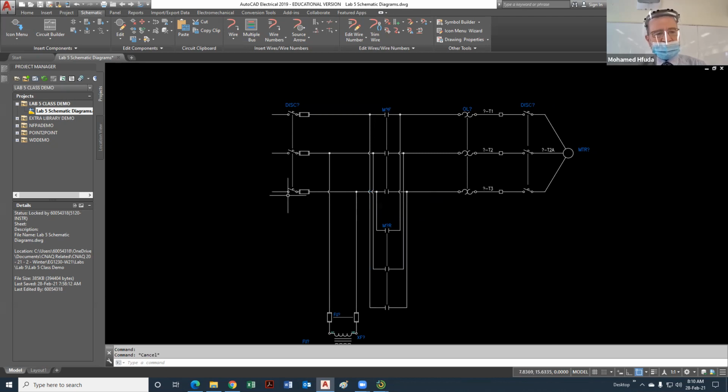If it is in forward, it goes straight to the third terminal. But if it is going through the reverse relay, it goes from the third phase to the first terminal. And that's how we are interchanging two phases of the motor. Obviously, we're not interchanging the phases of the supply.